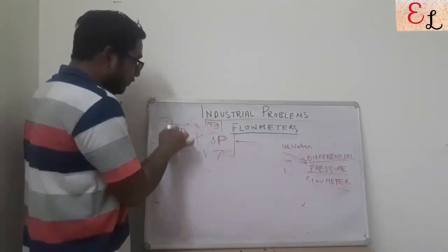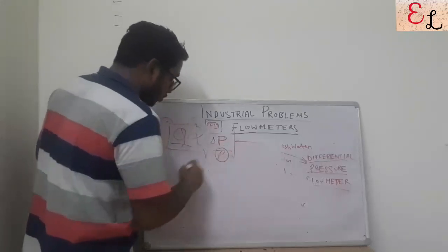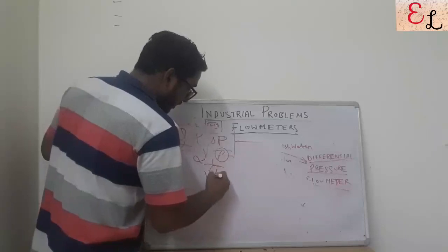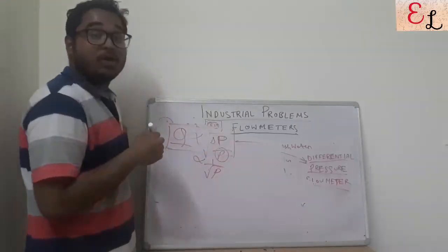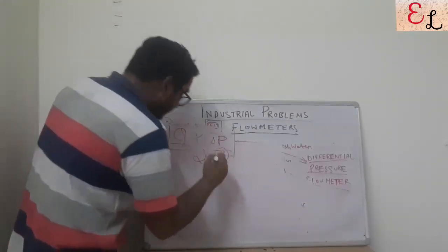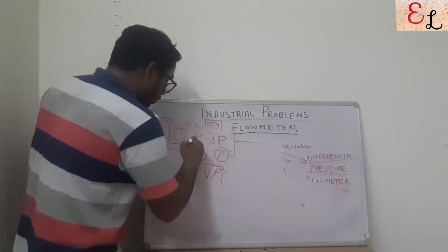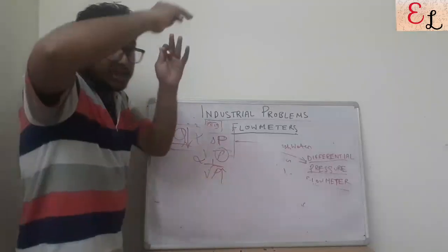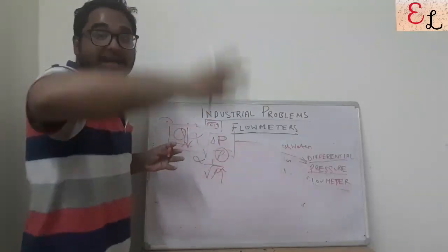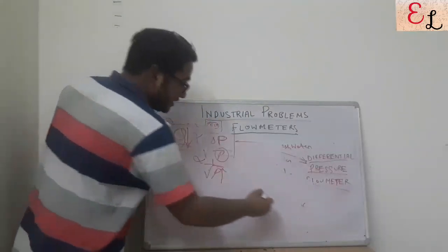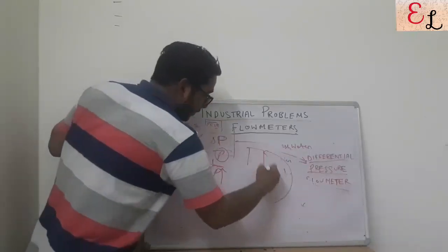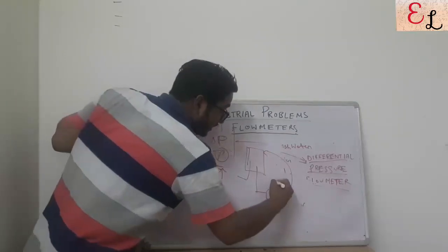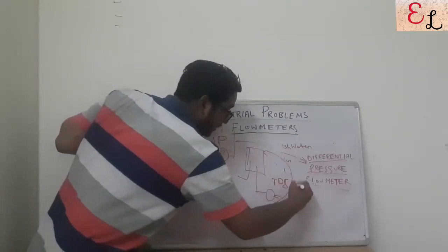Now we see that the flow rate measured is inversely proportional to root rho, that is, inversely proportional to the root of density. So if the density in the system shoots up, the flow rate will go down. And this is the exact system that is happening here. The slow build-up of dust in the circulating liquid is causing the TDS to go high.